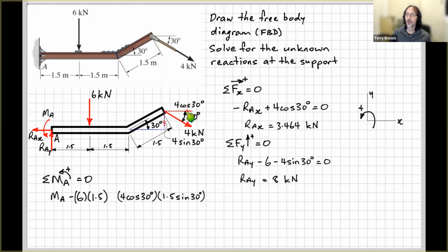So that's this horizontal component here. And its perpendicular distance from point A is this perpendicular distance that goes up here. So if we extend the line of action of that force, that's out here, and so the perpendicular distance will be up there like that. What I've got drawn in green there is our perpendicular distance.